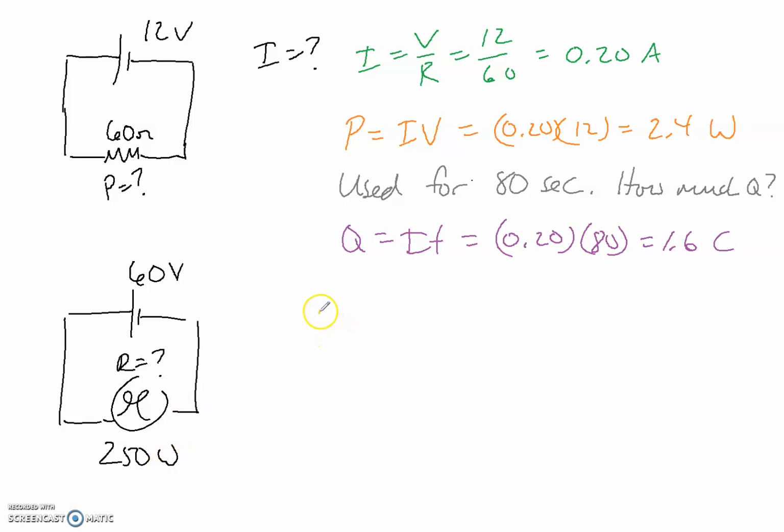They would do power divided by voltage, because that will give you your current. And once they had that, they would do Ohm's law, R is equal to V over I. That would work perfectly well. Or if you remember in the previous video, we spliced those two expressions together, and one of the power expressions we had was V squared over R. Some people would just jump straight to this one.